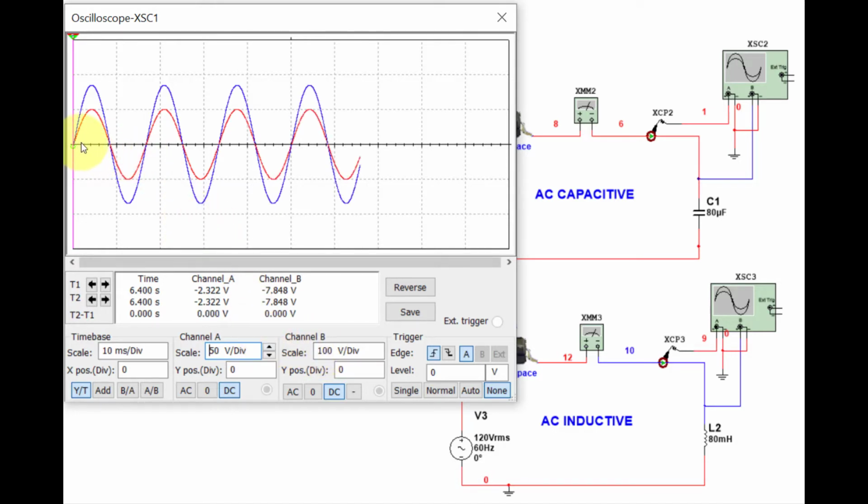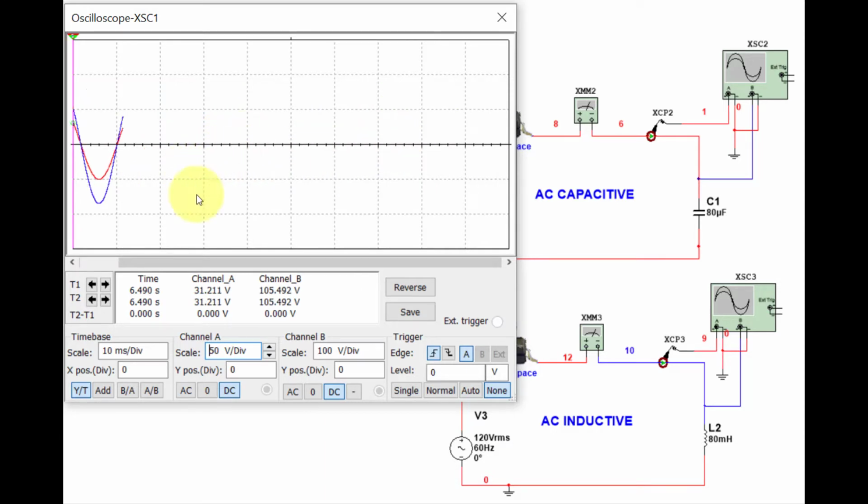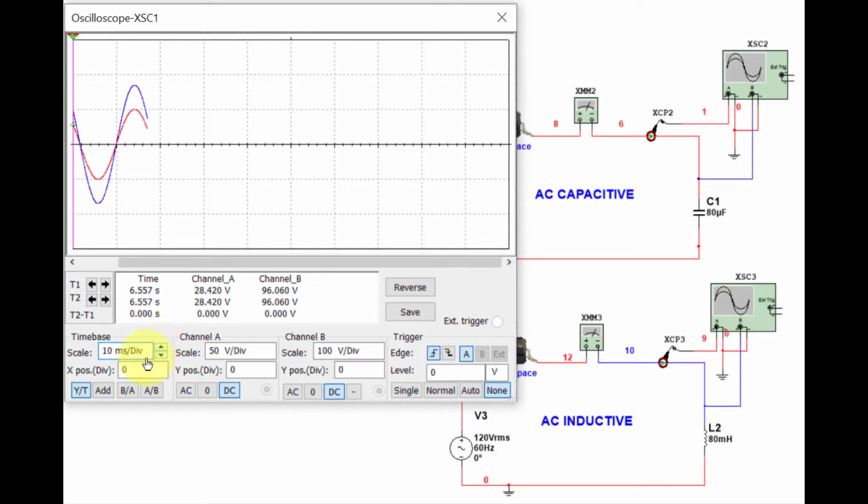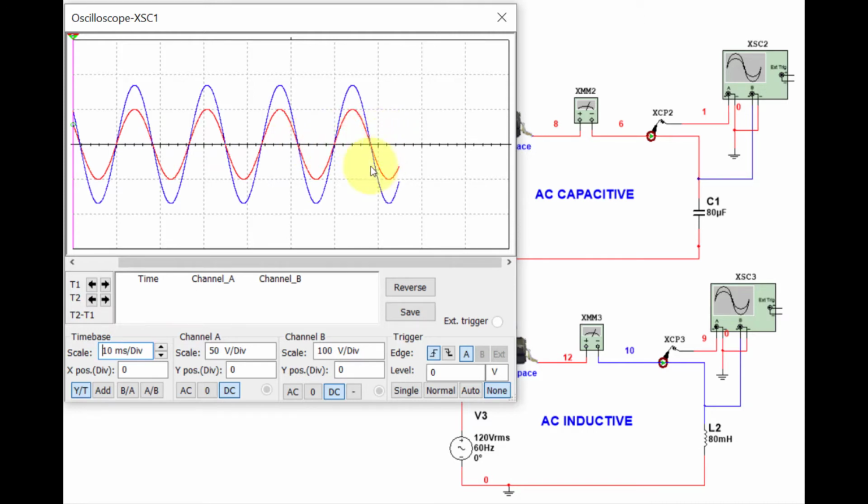Okay? Across the oscilloscope screen, you are measuring what's called period. And period is measured in time per division. So each one of these divisions is a set time, and you can adjust it by adjusting the time-base scale. Just set it to 1 millisecond per division, so I'm basically zooming in on one small part of the waveforms. It affects both channels when you adjust the time base. So voltage level is on the vertical scale, the y-axis, and time is on the horizontal or x-axis.